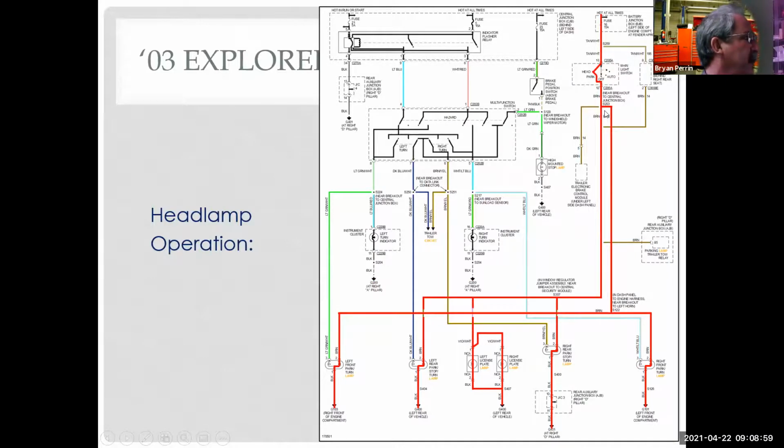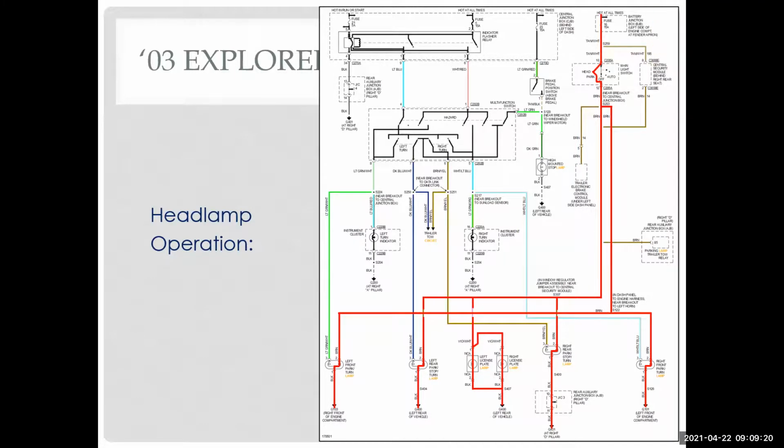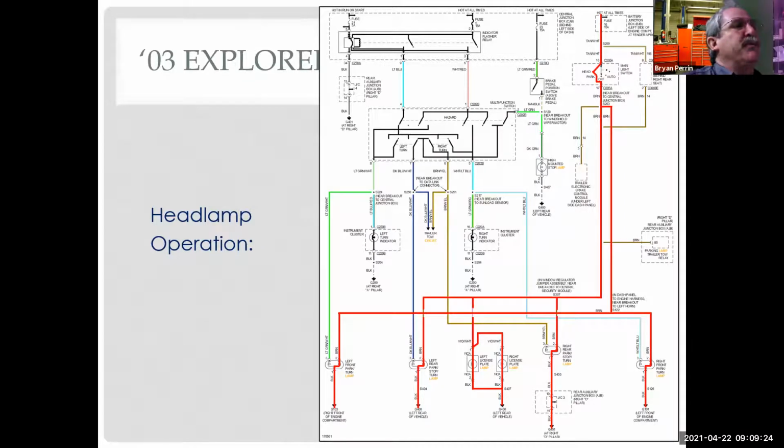I come through a headlight switch. And then from here, I'm going to come down and power up both my license plate lights, both my rear lights, and both my front lights. So based on what we've seen, is it possible that my headlight switch is the problem? Probably. Well, think about this. Do I use the headlight switch for all of these functions or only for headlights? For headlights.